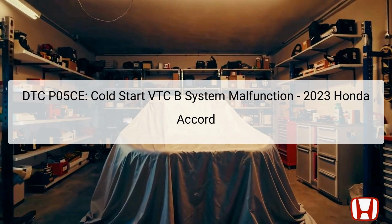The DTC P05CE pertains to an issue with the cold start variable timing control VTC B system in the 2023 Honda Accord. This trouble code indicates that there is a malfunction within the system responsible for adjusting the timing of the exhaust camshaft. The variable timing control system is integral for optimizing engine performance and emissions by adjusting the timing